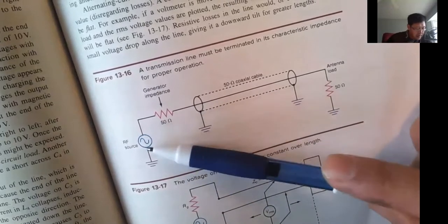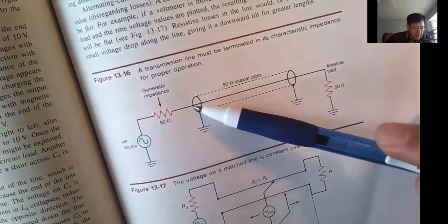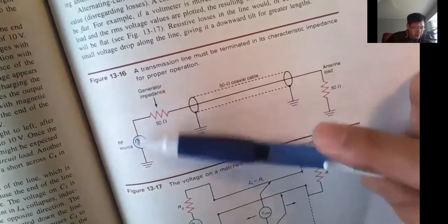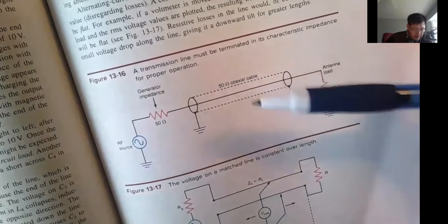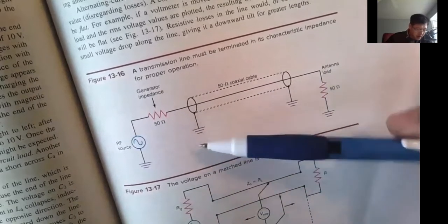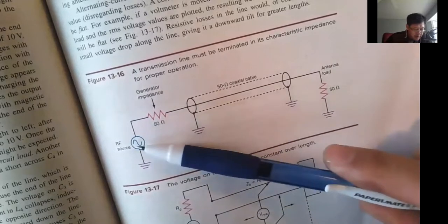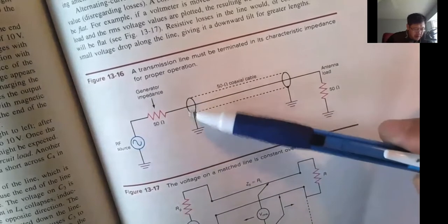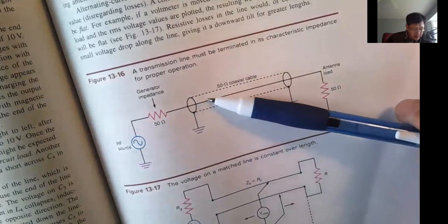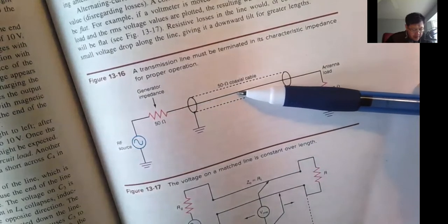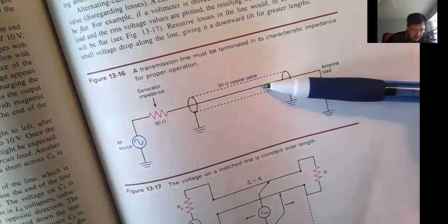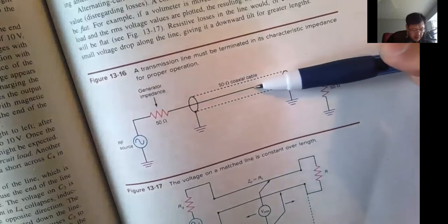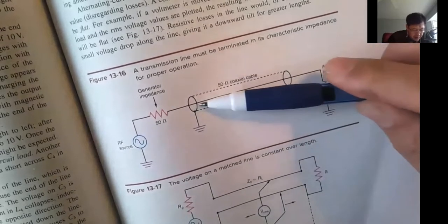So what happens is you have a power supply, and the power supply will have a 50 ohm impedance also. So everything is matched. Power supply has 50 ohm resistance, transmission line has 50 ohm characteristic impedance, and the load is 50 ohm. Once you turn the power on, half the voltage is on the internal resistance, and the other half is used to energize this coaxial cable. The energy travels at the speed of light multiplied by the velocity factor. So this travels slower than the speed of light, but it still travels very fast, for example, 80% of the speed of light.